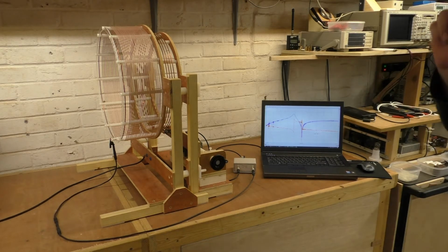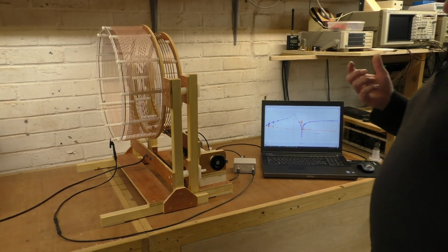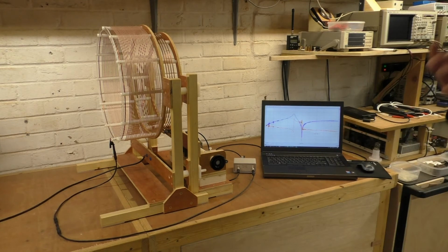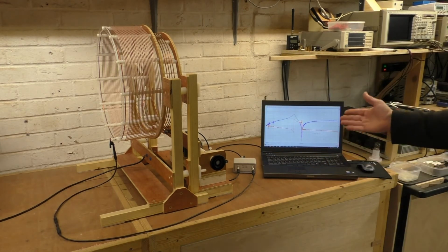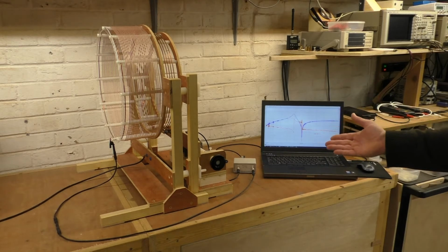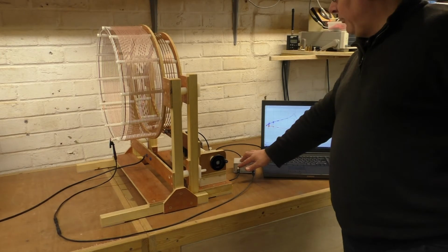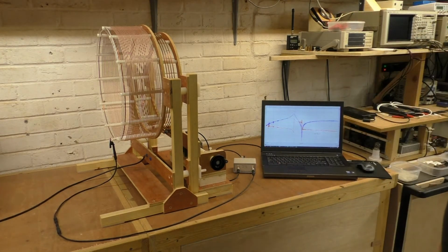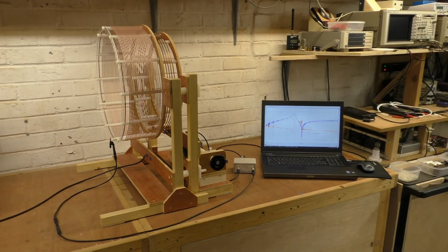One thing to be careful of here, obviously, is that we have got voltage magnification, but it is not acting as an amplifier. It's a passive element, so the amount of power that's fed back to the input will be less than the amount of power that we put out. Obviously there is some insertion loss involved in this component.